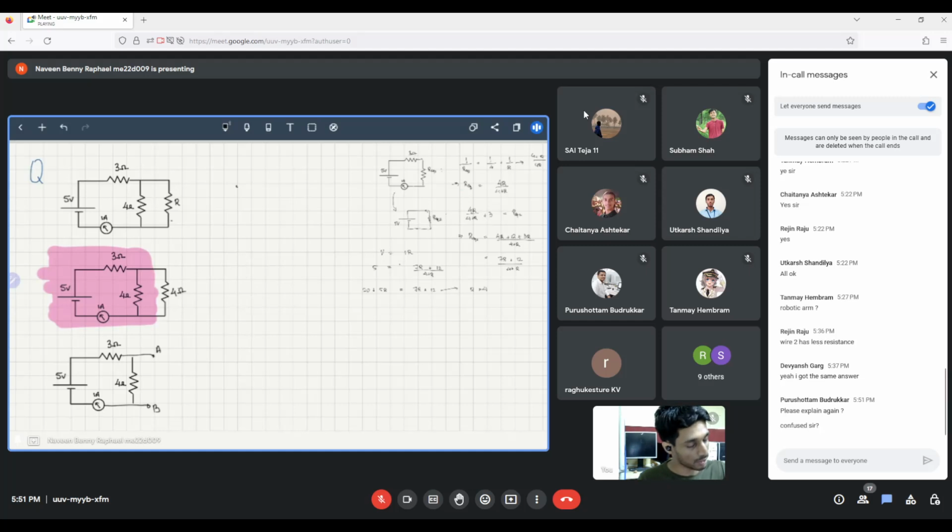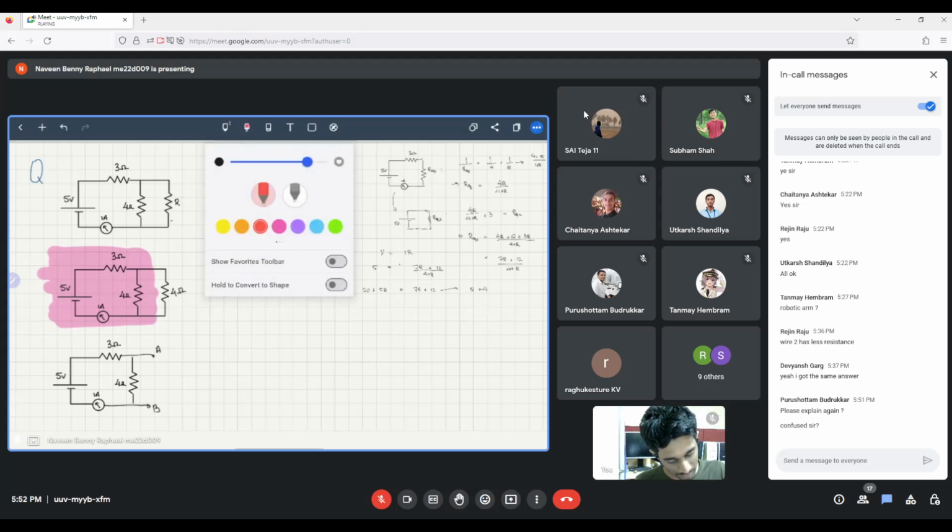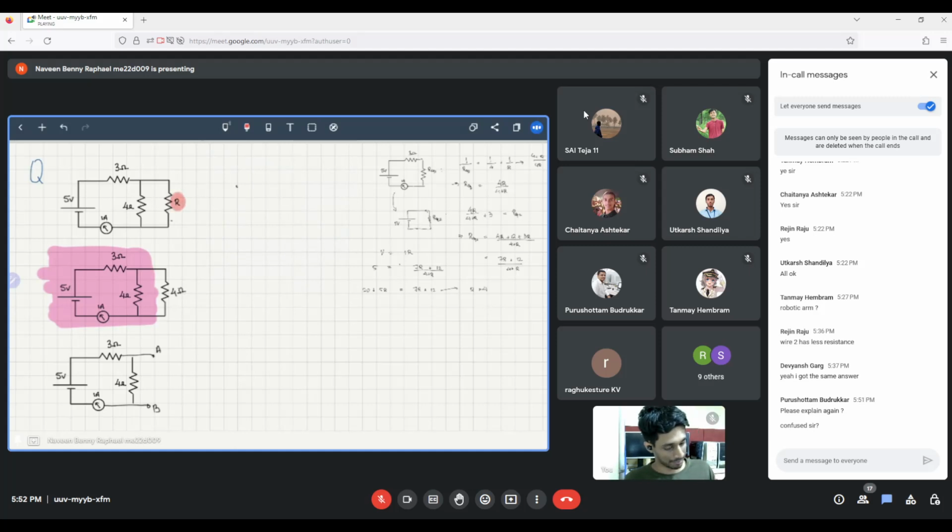Using the normal approach, we found that the resistance is 4. We found that this is 4, right? If this is 4 and this is 4 and we have 1 ampere flowing through the entire circuit, what does that mean? These are parallel resistors. Parallel resistors will try to share current, and how much current they share will depend on how much resistance there is.